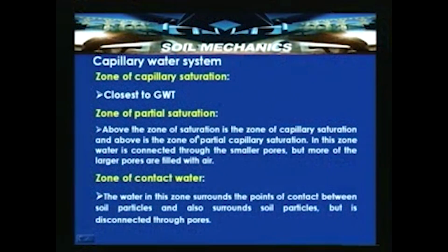So, above the zone of saturation is the zone of capillary saturation, and above that is the zone of partial capillary saturation. In this zone, water is connected through smaller pores but more of the larger pores are filled with air. So, when more of the larger pores are filled with air, that tends to be a partial